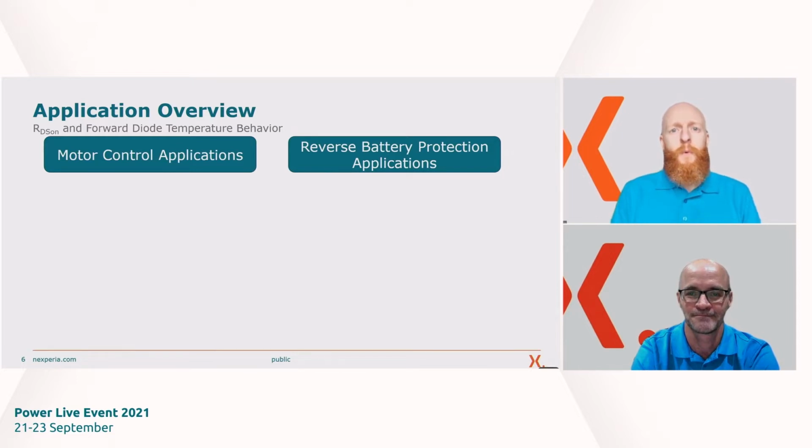So why do you care about the thermal interdependency and that kind of behavior being described in our models? What I'd like to do is drill down to a few examples. But first off, just start by saying that we're all power electronic engineers, and as a consequence, we also need to be thermal engineers. We need to have a good appreciation of the thermals in our system. The reason being that you have a PCB and you have many components in your design, and you need to make sure you're operating within their safe operating limits.